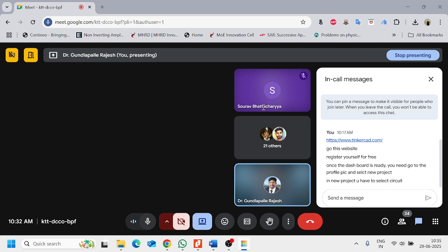Now loop is a continuous loop which will keep on executing. Here we have a function called digitalWrite. Pins 7 to 12 are digital pins, isn't it? So what we have to do is write onto the digital pin. We have to give some voltage there. If you want to give the voltage, or if you want to give the status as high, you have to write digitalWrite.